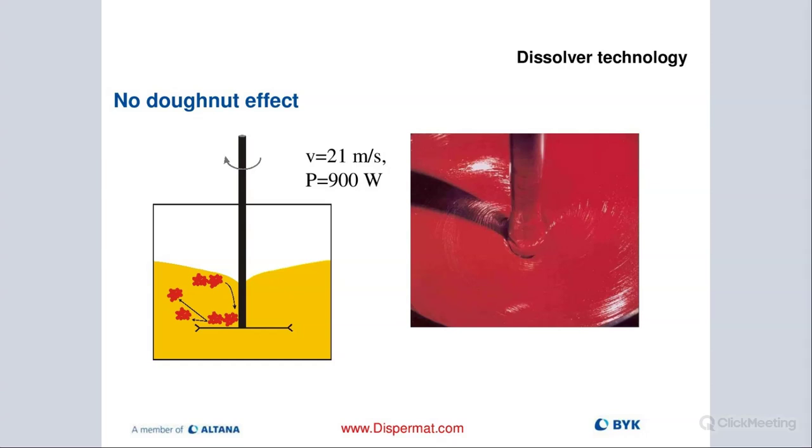But we are basically not ever going to see a donut, because the donut wouldn't be able to form, because the material is so thick that we are not able to actually see it visually. So we rely more on the data on the display to tell us, hey, we're doing a good job, we are pre-dispersing, and then maybe do a quick, dry sample, grind check with the grind gauge, giving us the indication, okay, we are moving in the right direction.